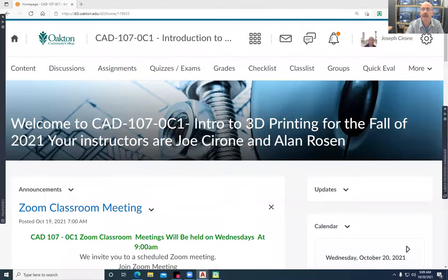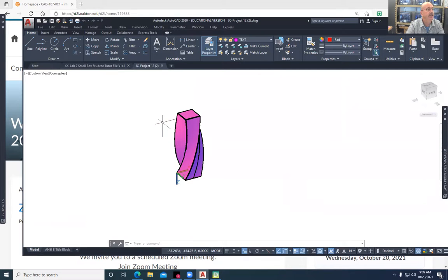We printed these projects for the vase, and I'm going to show what the project looked like. Essentially, what we did was we designed them in CAD. When you design them in CAD, we're not using the shell command, because we want to bring them into the slicing software and use the Spiralize outer contour command, which will print a one layer thick contour and then just goes up in the Z-axis every time. So as we start to look at that, we're going to look at how that turned out.